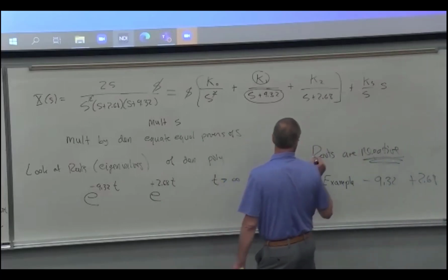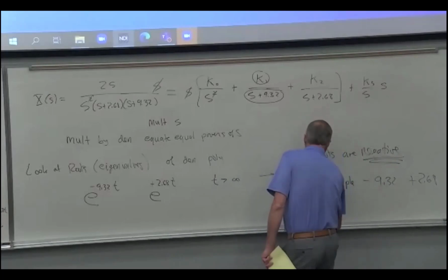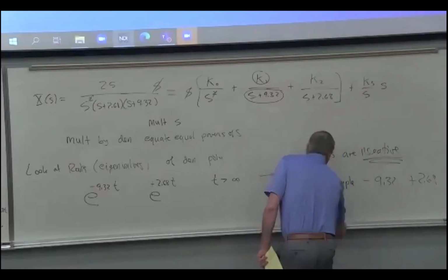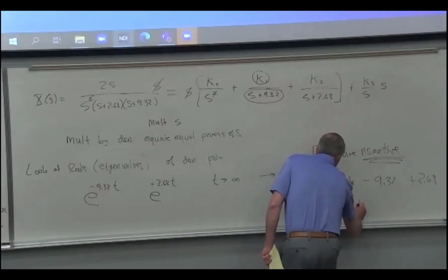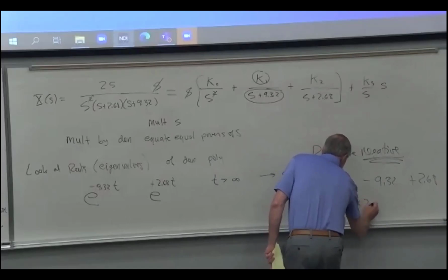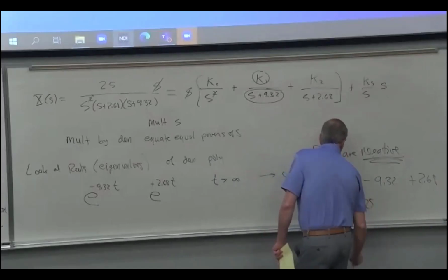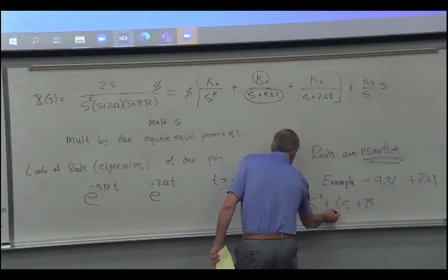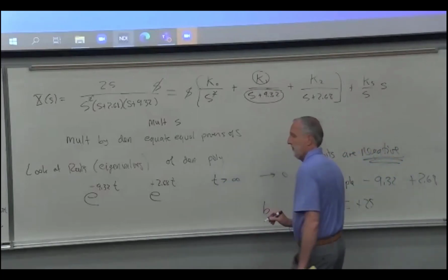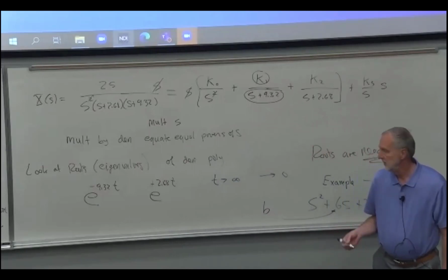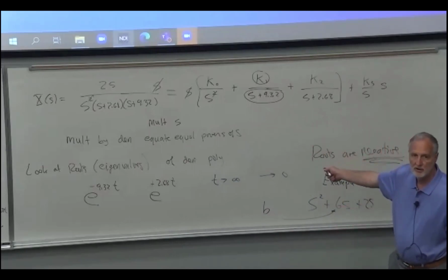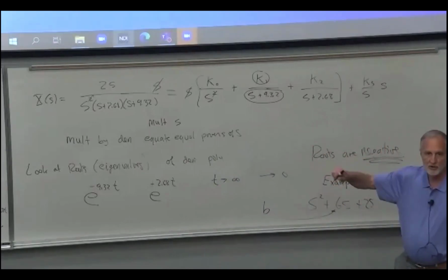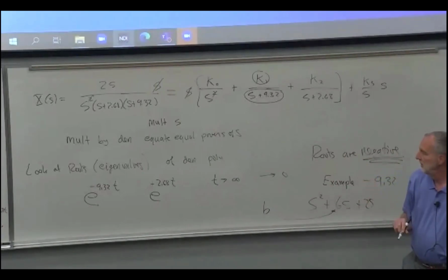Sometimes with polynomials like s squared, let's say we reduce the damping to 6 in that polynomial. So this is b here. Let's look at that. Because we had b equal to 12, and we got those roots. If b reduces to 6, we've cut down on the shock absorber, the damper. What happens?